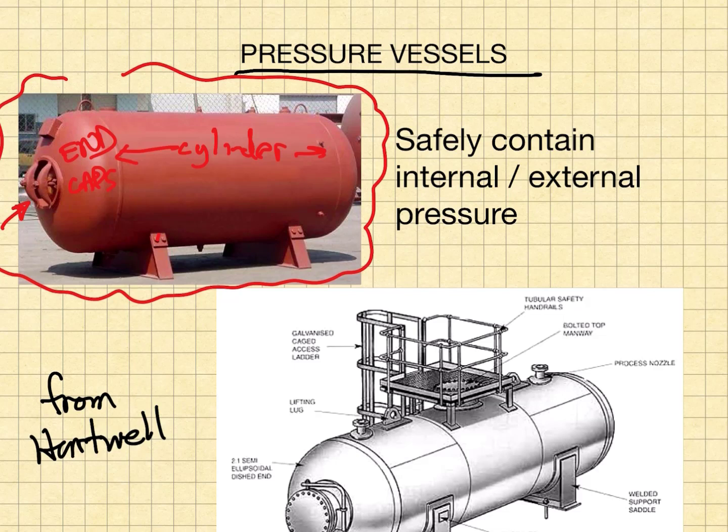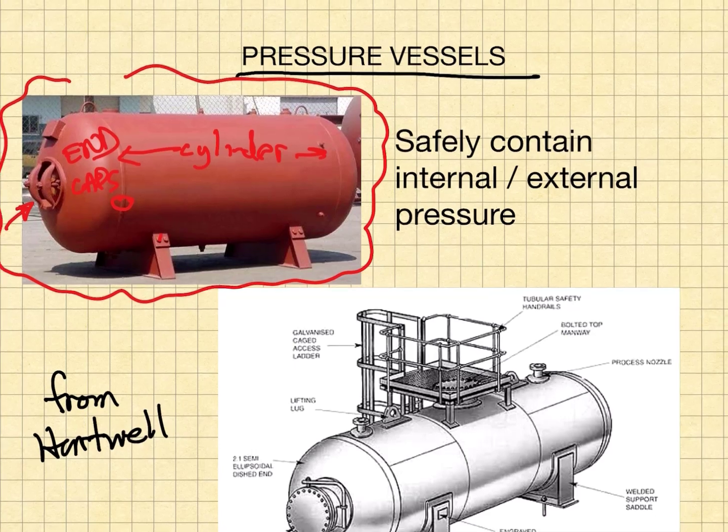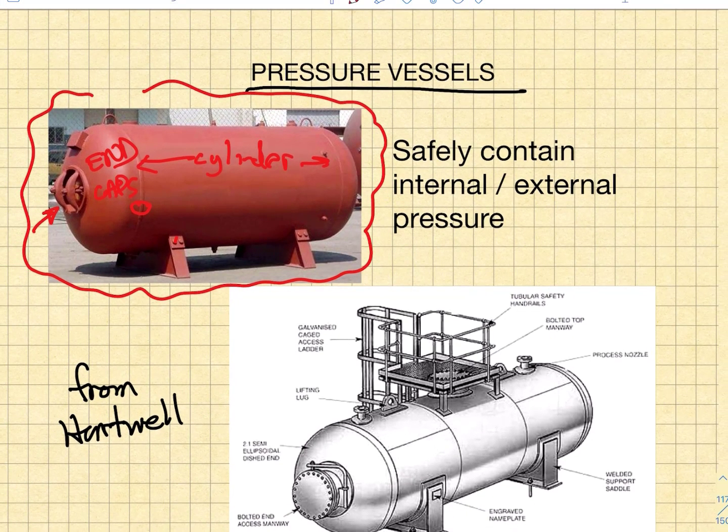So we need to understand what are the stress states in the cylindrical portion of it, what are the stress states in the end caps, what are the stress states near any access holes that generate stress concentration factors, and what are the stresses in the transition from the cylinder to the end cap. We must design any system that carries an internal pressure to be able to safely carry that internal pressure.